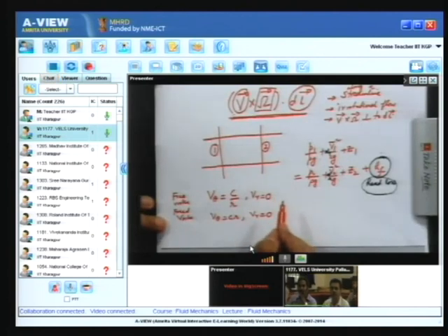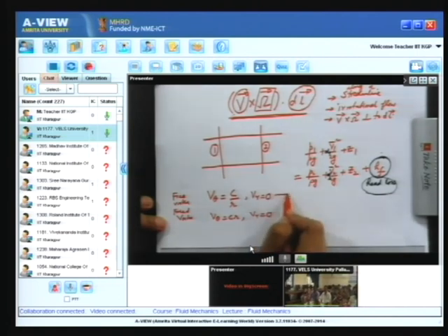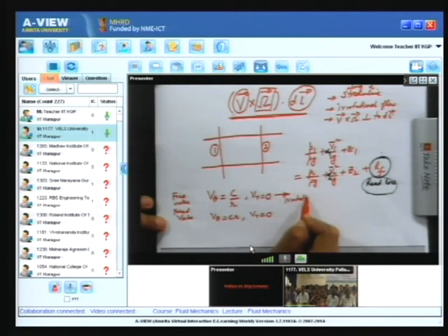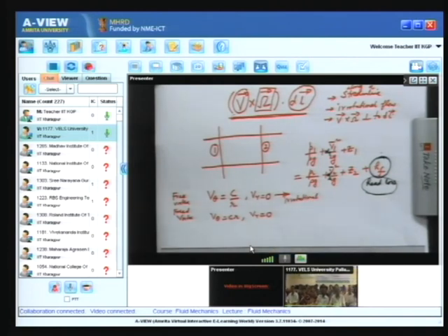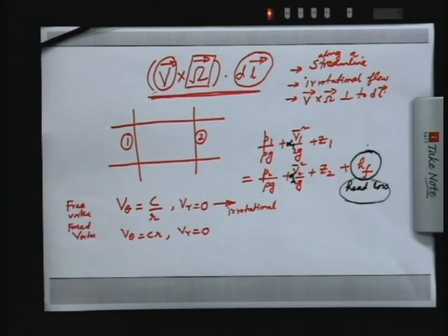The answer to your second question: it can be shown that the free vortex flow is an irrotational flow. So you can apply the Bernoulli's equation in a free vortex flow between any two points in the flow field, no matter whether they are located along the same streamline or not, provided other conditions of the Bernoulli's equation are satisfied, but the same thing you cannot do for a forced vortex.